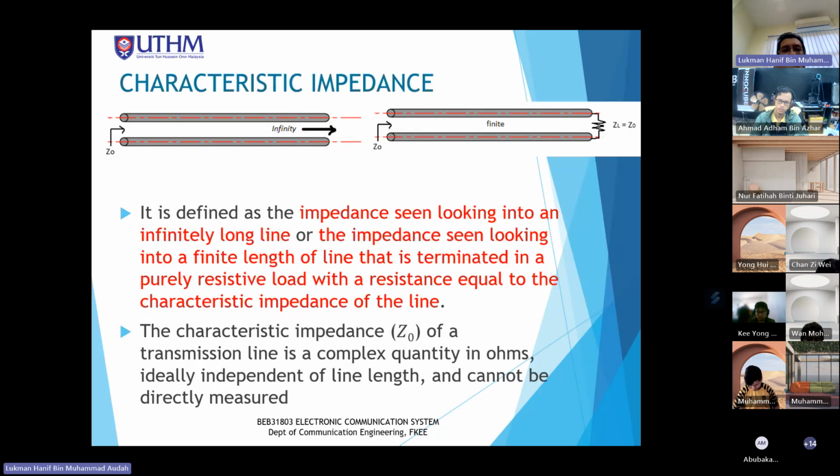And we have also seen about the characteristic impedance. Here are two pictures. Imagine that this is picture A and the other one is picture B. So this is a different picture. Characteristic impedance is actually an input impedance for a long transmission line.